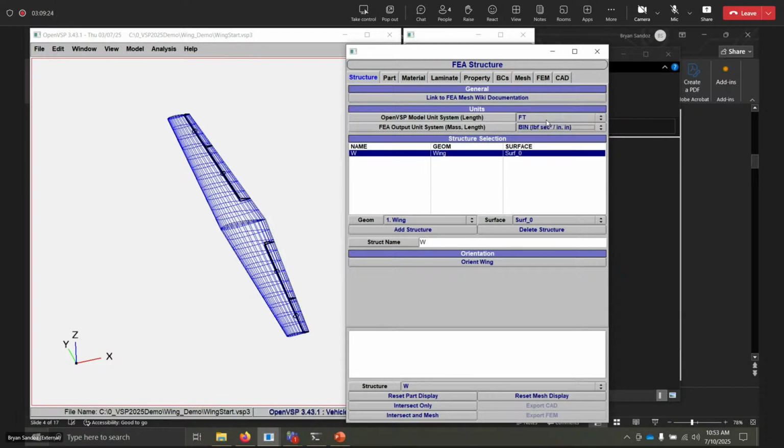And then I'm going to use the more common inches unit system for the structural analysis. This way I get stresses in PSI, and that works better. I will say there's a fairly robust system with the materials and properties for defining units appropriately, so you can keep track of your units. If you have materials in all sorts of different units, you put them in the units they're in, and it will convert everything to the right thing. So that's really useful.